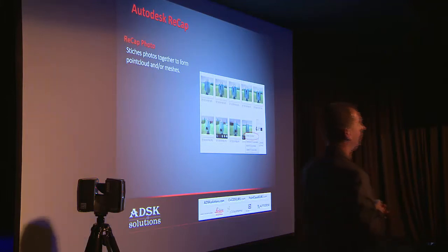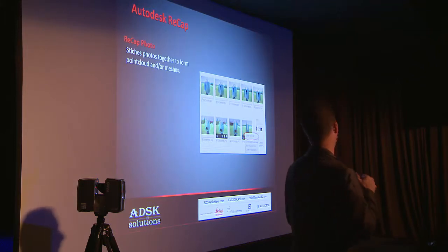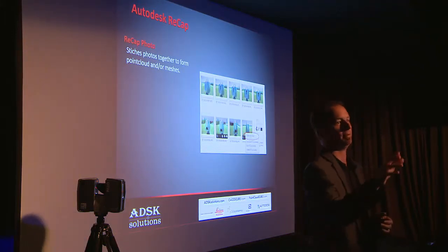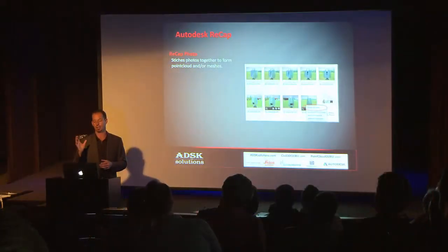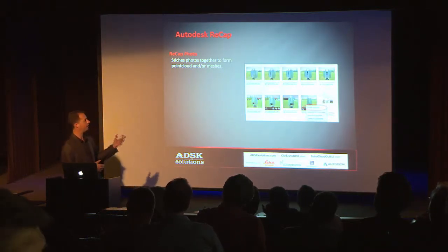The hardest part for me, if you go back and try this: you have to have an Autodesk 360 account. You also have to have Google Chrome. I was trying to use Internet Explorer. It probably took me 10, 15 minutes. I kept dragging and dropping everything, and it wouldn't work. Once I figured that out, I dragged and dropped the photos. Literally, it was this easy. Which ones do I want to use? I got rid of some of the bad ones that I didn't want to choose.